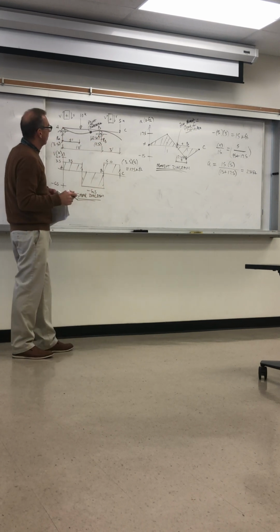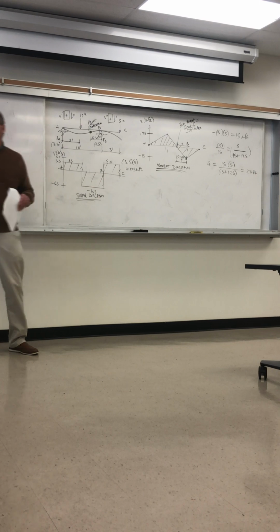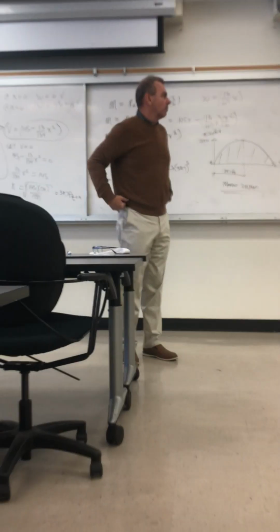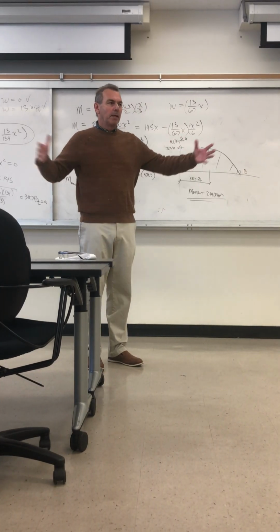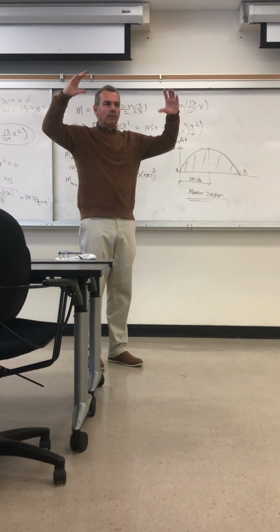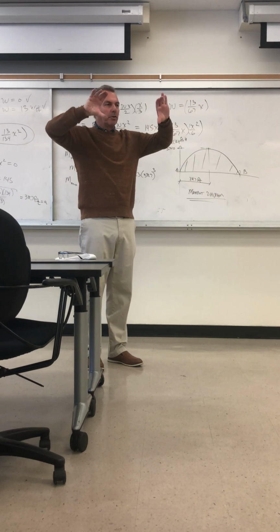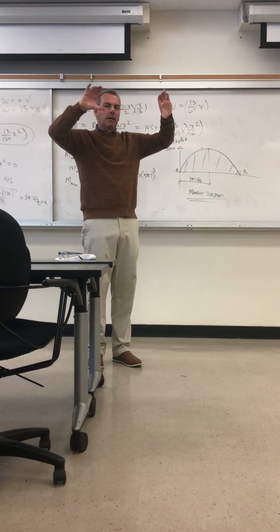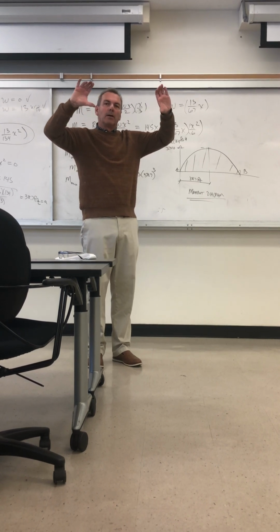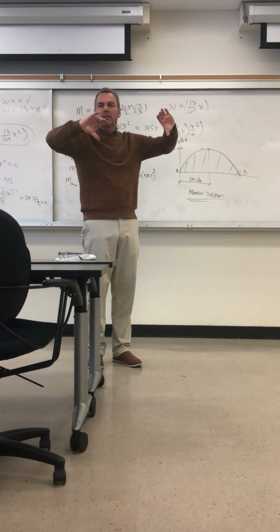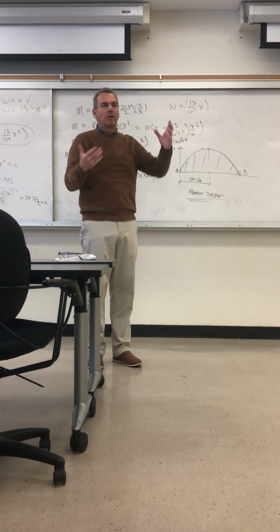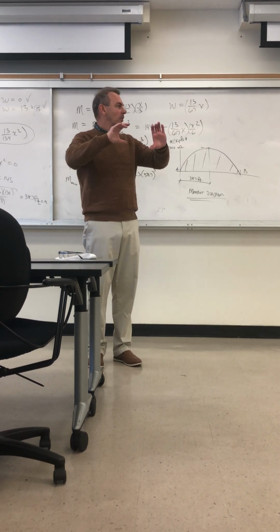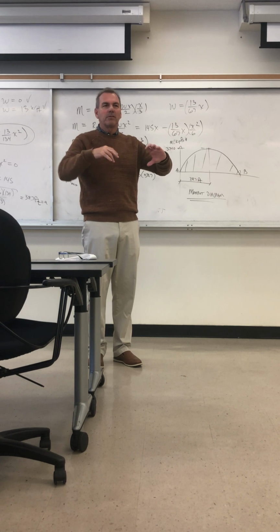This is where it's switching from negative bending to positive bending. It's really important to know that because if you're designing, let's say, a reinforced concrete main span for a bridge or a big reinforced concrete beam, when you have loading, it deflects down, you have curvature like this, let's say a simply supported beam. And so in that case, you'd have positive bending. The concrete will crack in flexure at the bottom, at the tension side, and if there's no steel reinforcement, it just opens up and collapses. And so the steel reinforcement has to be on the tension side.